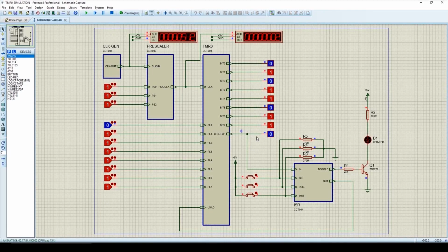And whenever the timer 0 interrupt flag is 1, timer 0 will be loaded with this value, that is FE. Here we can observe that on each interrupt, this value FE is loaded to the timer, and the interrupt service routine is executed after every 2 clocks.